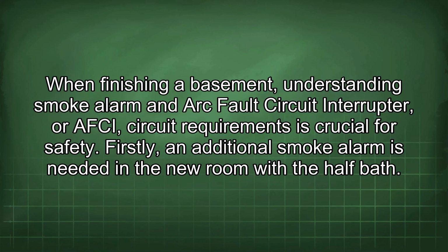When finishing a basement, understanding smoke alarm and arc fault circuit interrupter, or AFCI, circuit requirements is crucial for safety. Firstly, an additional smoke alarm is needed in the new room with the half bath.